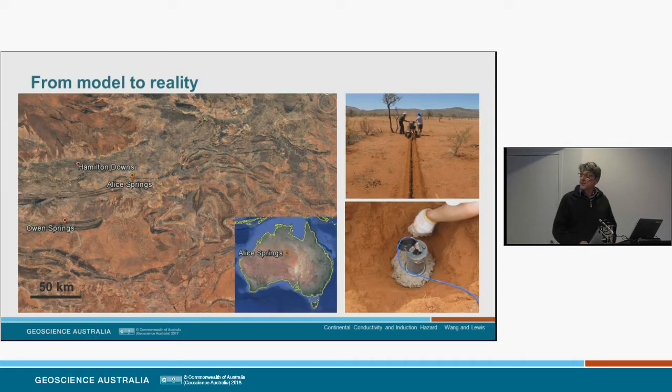So this brings us to this final section of the talk. The magnetic field is routinely measured at magnetic observatories and elsewhere in Australia, and over many decades for some of the observatories we have. But in Australia, the electric field is not monitored routinely in an observatory type situation. It's only generally monitored for short-term field campaigns. But it's the electric field that's required as input to the engineering step of GIC studies.